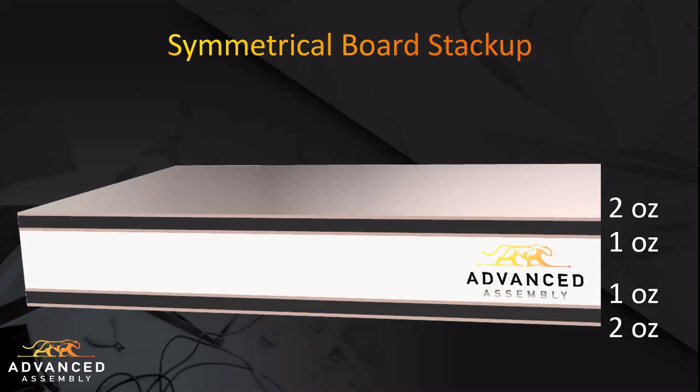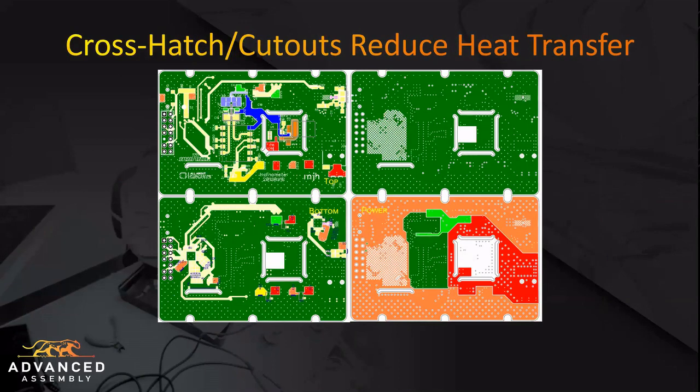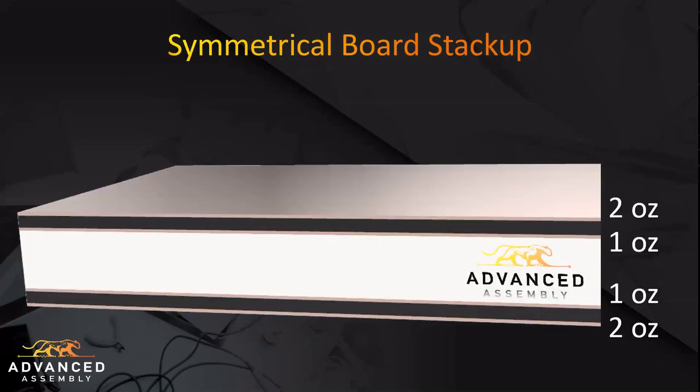If you have a board with uneven symmetry, it's going to have greater flexural strength on one side versus the other. And that means when the board heats up, as soon as it goes through, it's just going to flex and cup. It could bow. I kind of alluded to looking like a Pringle chip. And there's a lot of criteria, especially for aerospace, weapons, and defense, for flatness, for bow and twist. And if something is uneven copper weight, and especially heavy copper in that, it's not going to pass. It's ultimately going to be rejected in final QA.